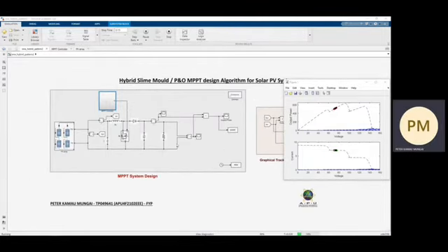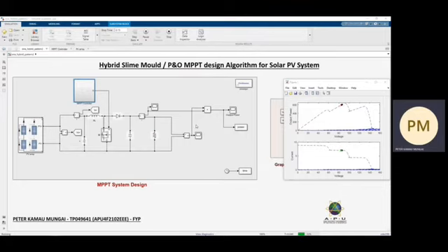The main function of this maximum power point tracking algorithm is to develop an effective tracking algorithm that can be used in practical PV systems whereby harvested power is under changing insolation or under changing weather patterns. To develop this maximum power point tracker, we're able to overcome limitations of conventional techniques such as perturb and observe, which have limitations such as low tracking efficiency, steady state oscillations, and various transients. And to implement the above maximum power point tracking controller algorithm is a real addition to the world of photovoltaic systems.